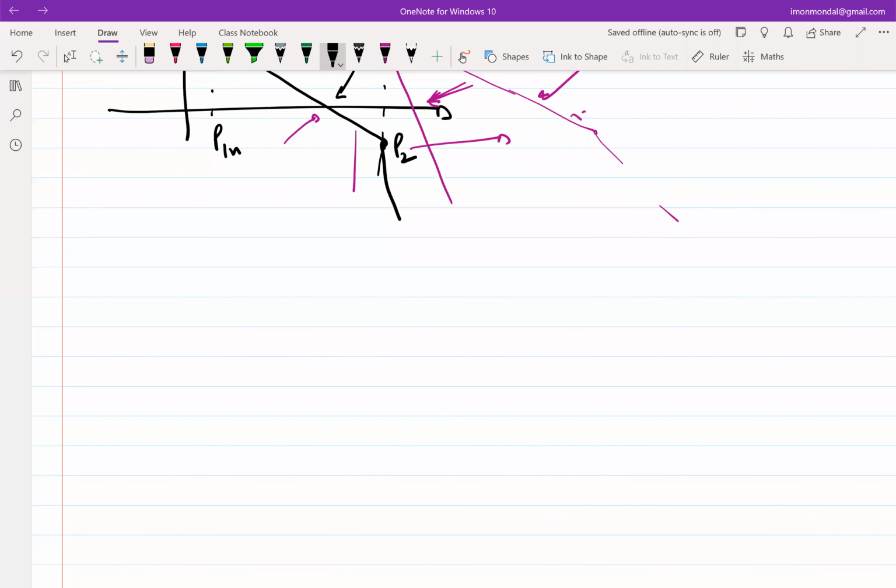And even if you don't have more of these blocks cascaded together, you have internal capacitances which we have conveniently hand waved off. So essentially the system can be of higher order. Okay, so let's assume such a system which has L of S to be A0 by (1 plus S over P1) whole cube.